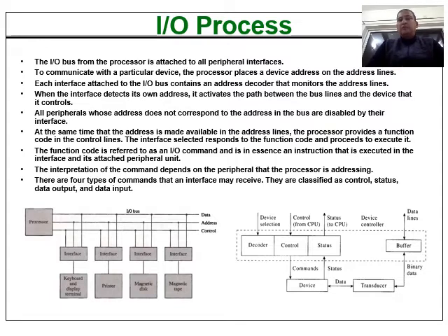When the CPU places a particular address on the address lines, this address is read by the decoder, which uses it to identify which particular device the CPU wants to talk to. There may be two cases. Either the address that the CPU has put on the address lines is for the device that this interface is controlling, or it is the address of some other device.